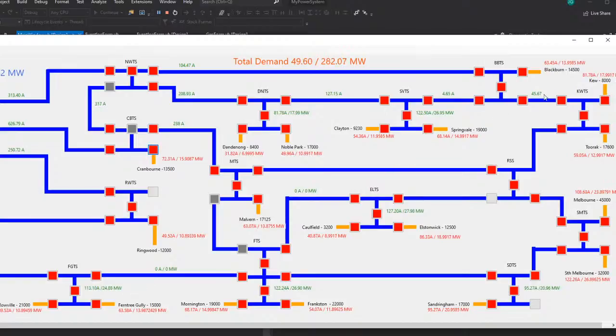Anyway, right now I'm trying to, as if all the breakers were closed, get the currents to chop around how they would. Like, I can see I've got 400 in here, then I'll lose 80, 81, then I've got 338 and lose another 122 amps. Then I've got 216 amps keep going on. And then I've got this 210 that comes through, but I'll lose 63. And then that comes in here, but it mates with what's left, and I've got 362. Anyway, that sort of thing.